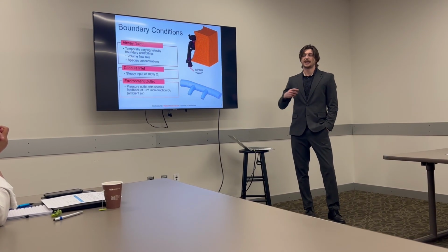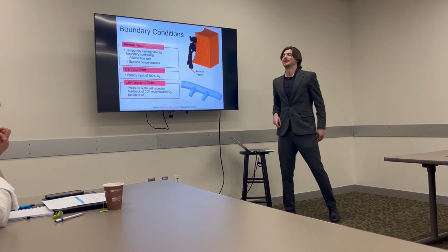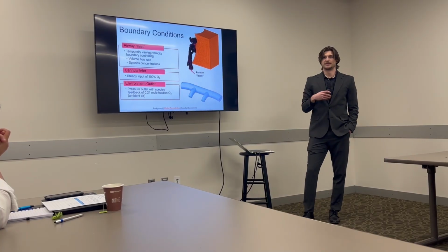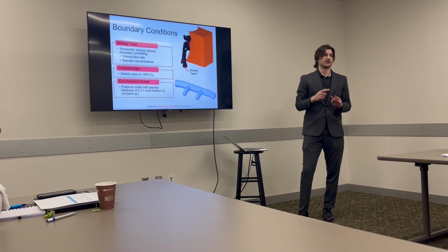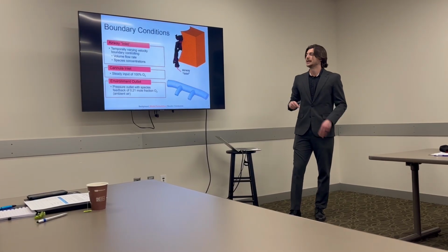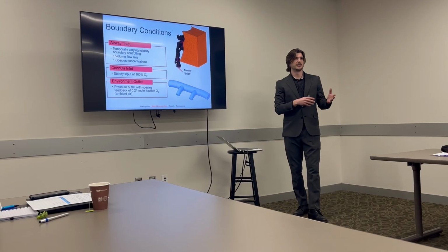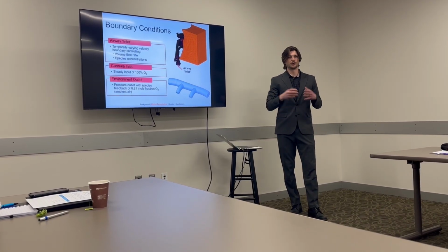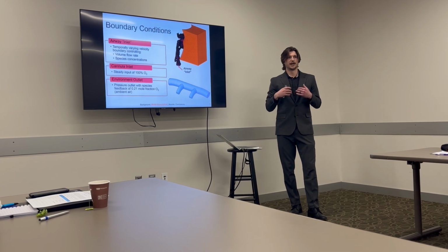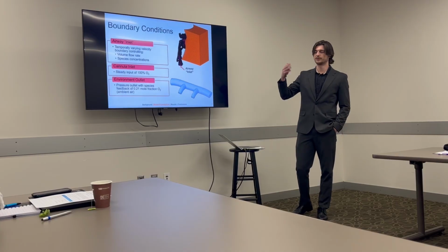As the model is inhaling, flow is leaving out the airway inlet, and as the flow is leaving, we're tracking the total volume during inspiration of oxygen, nitrogen, and CO2 that's leaving the domain. Then prior to the initiation of the expiratory phase, we take the total volumes that were inspired and set the species concentration for the subsequent expiratory phase.